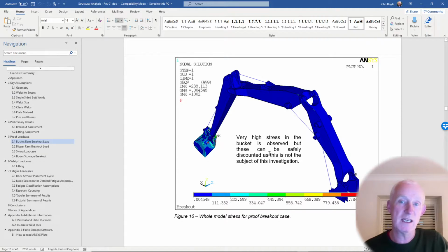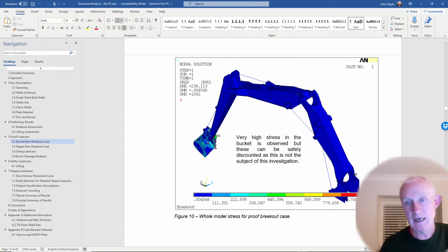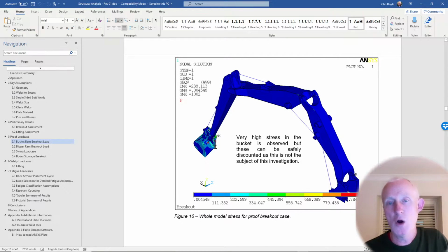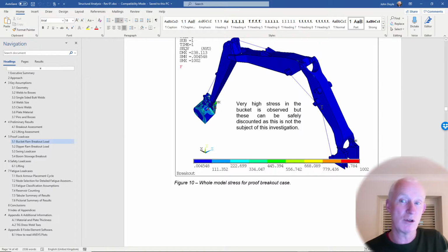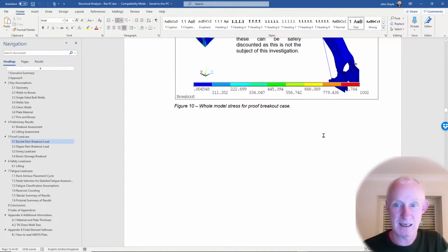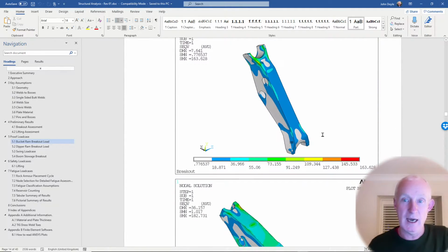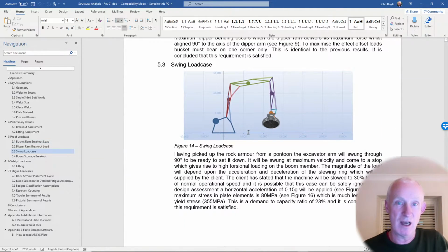Now, for some of these load cases, see here I've got the load to be even more onerous. I've put the bucket breakout force not along the whole surface there, but I put it on the corner of the bucket. And this is maximizing, so I'm getting some twisting of that arm at the same time. So I need to use a 3D model to do that. So I've copied the model over, so the analysis is slightly bigger now. And again, we can look in detail at each of the arms there.